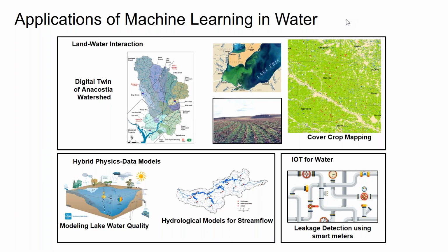One of them is in areas where there is no calibration data available, no gauge data available, in a lot of the developing part of the world, but also in the US. We are creating a time series of the size of these water bodies, of this water area, and that is serving as a hydrograph to train the model. If you have a hydrology model showing that an area got flooded, now we can go back in time for the last 30 years and see what the surface extent map was on that day and create, basically, a surface hydrograph to calibrate the model.